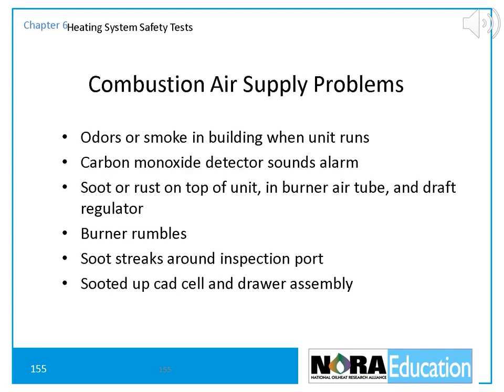Combustion air supply problems. One of the major causes of CO events is insufficient combustion air in the combustion appliance zone. This can be a hard problem to diagnose because when entering the CAZ, we open the door and this allows the pressure to equalize, supplying fresh air to the room, temporarily fixing the problem. So we have to look for clues that the burner was starved for air when the problem occurred.